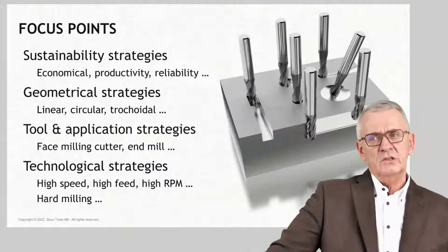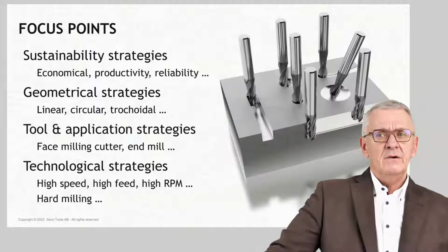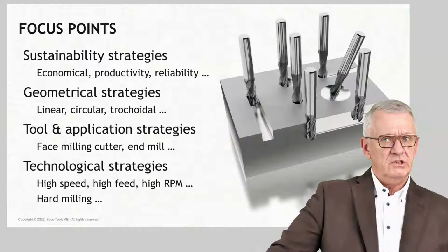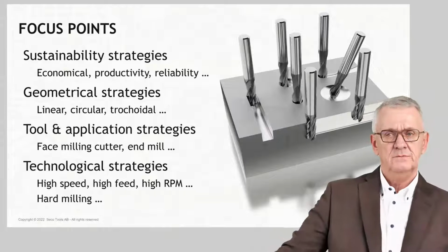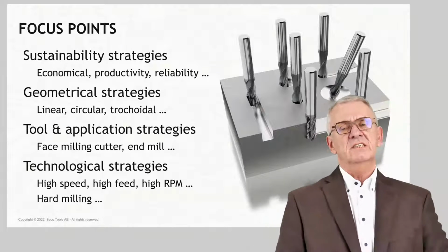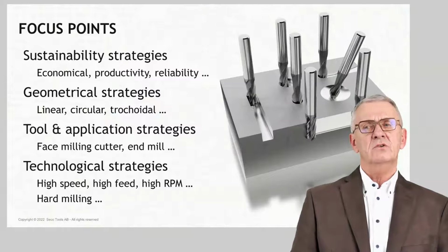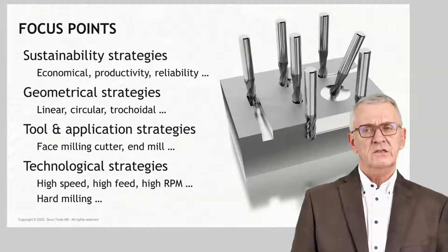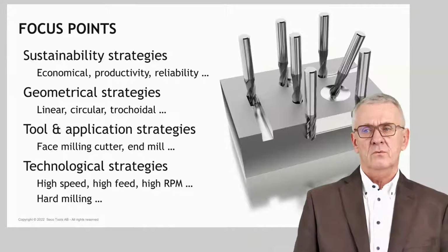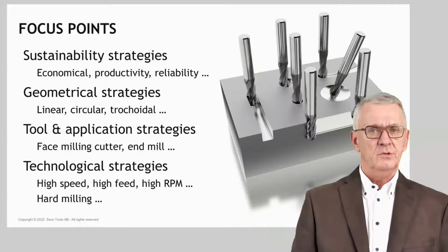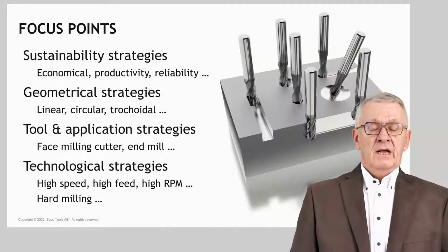It's about economical thinking, productivity, reliability, that type of thing. We also have to talk about what is referred to as geometrical strategies, which is basically: how do I move a milling cutter? How do I move a tool? Linear, circular, trochoidal, whatever. There are multiple possibilities there.